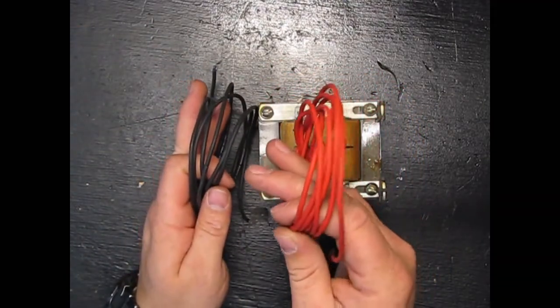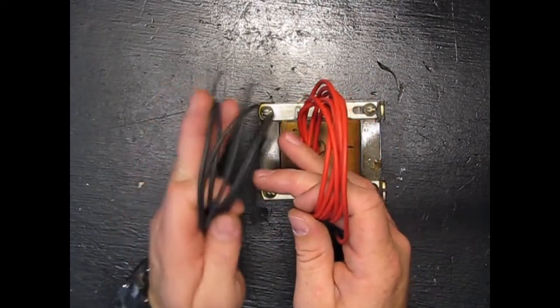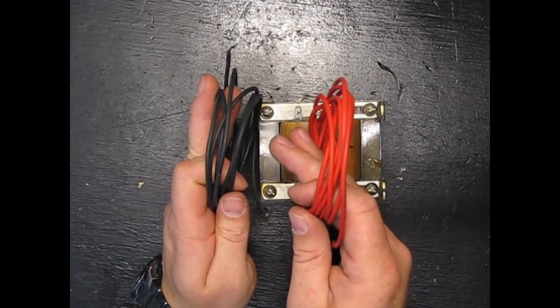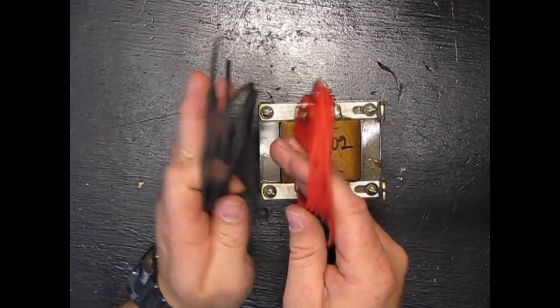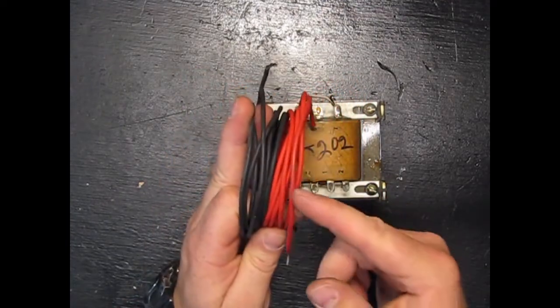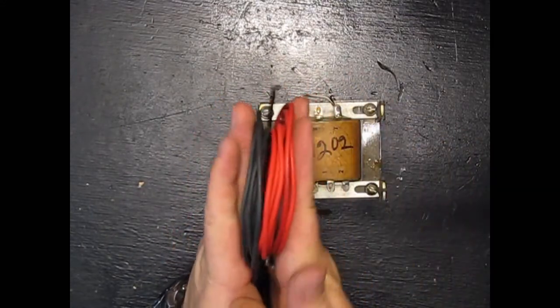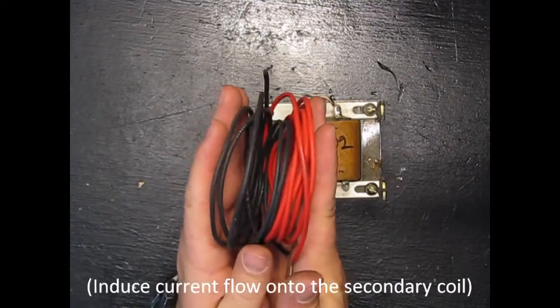So if you have 100 turns here and 50 turns here, and you're running 120 volts through here, you would get 60 volts here, because the electromagnetic field will transfer the electricity from one coil of wire to another.